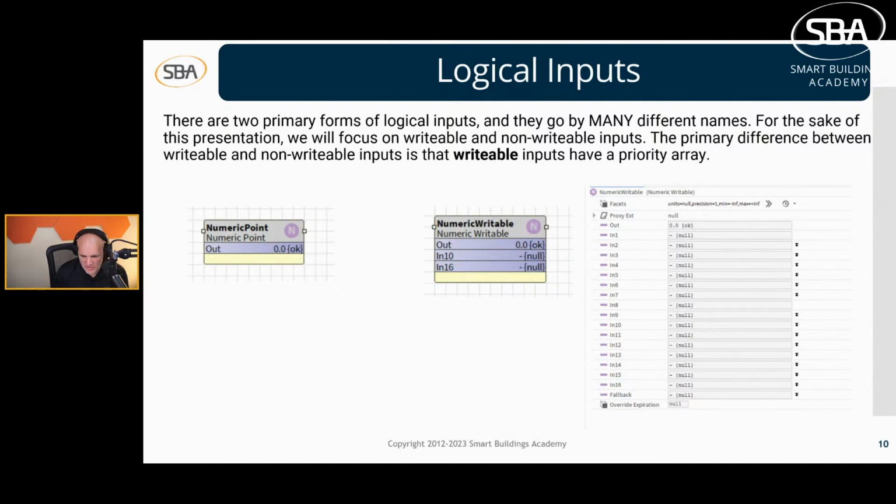And I know some of you are going to say, well, Phil, there's a variety of ways you can override AIs, analog inputs or binary inputs, by bringing them out of service. You are correct, but I would argue that that's for testing, because technically when it's out of service, it should be out of service and no longer readable by the controls program. But that's nuanced.